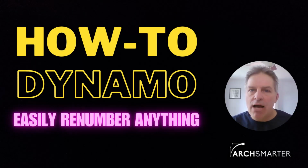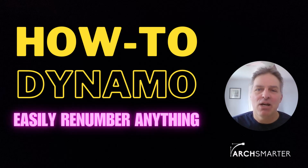In this episode of How to Dynamo, you're going to learn how to renumber elements in Revit using Dynamo. So, has this ever happened to you? You just finished numbering your rooms or your doors or your parking spaces, and then you realize you forgot an element. Or maybe you add an element and then you need to renumber everything to get it in the right sequence. Or maybe even, man, I hate this one, the renumbering standard changes on your project, and then you need to go and redo everything.